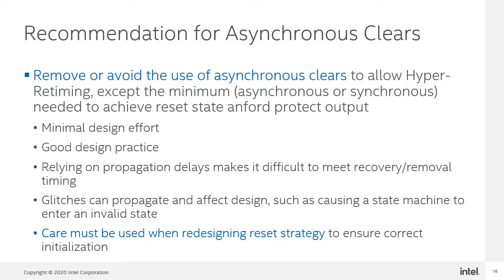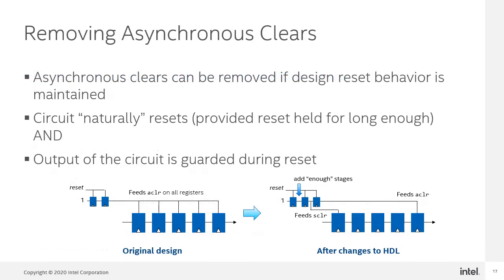Use caution though. Modifying the resets to your design changes how your design initializes upon power-up or after a reset is issued. So you must make sure you understand the FPGA's reset behavior, and you should revalidate your design again with the modified reset strategy. This slide provides an example of how resets can be removed from a design.